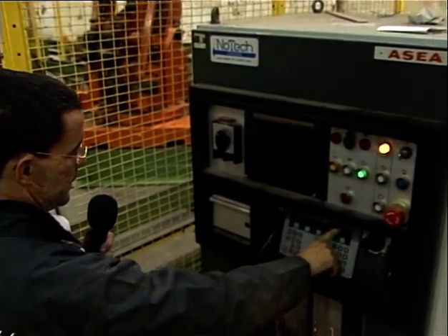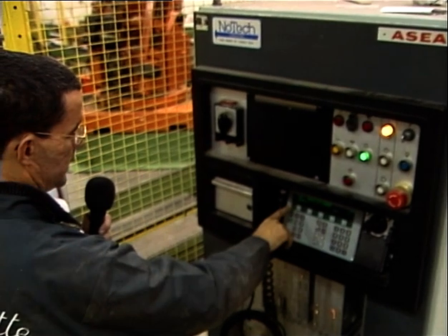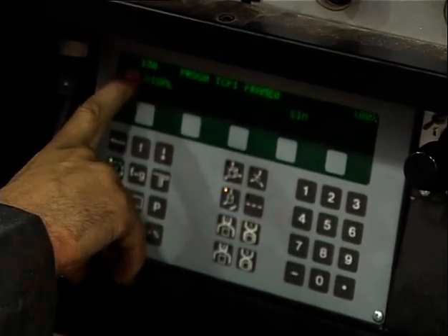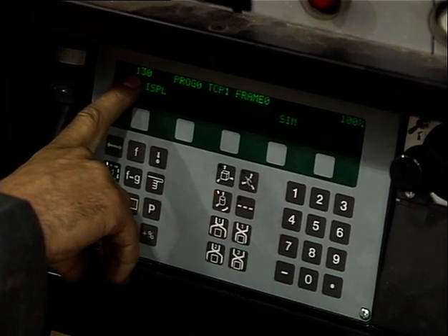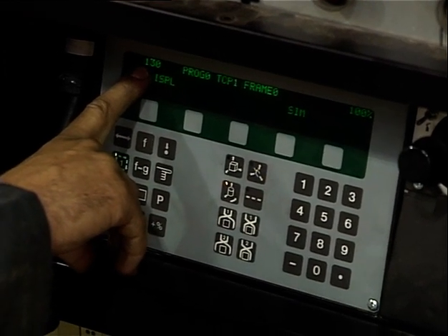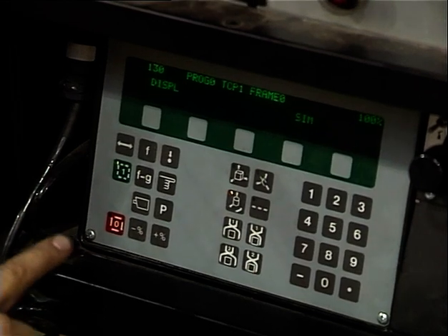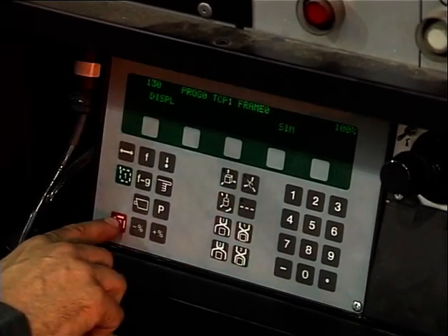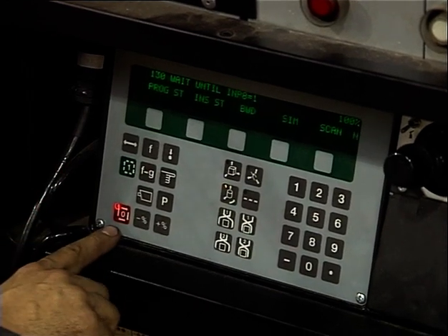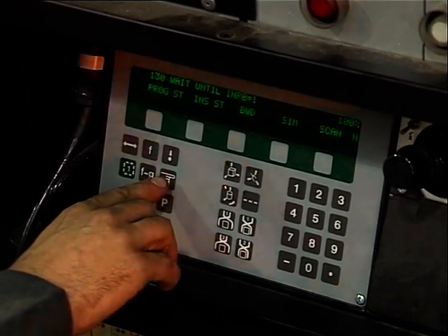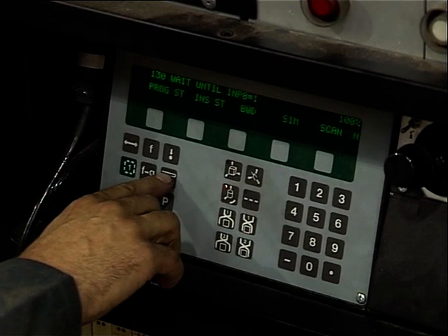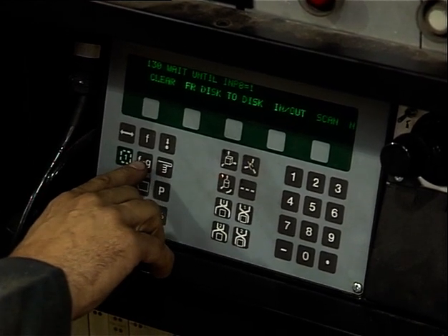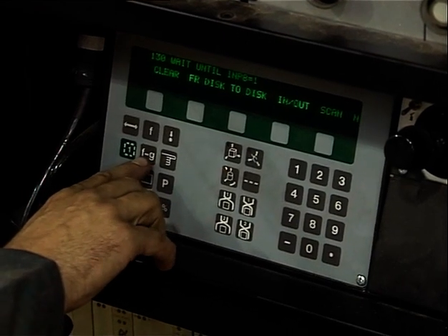You see on the screen of the teach panel the instruction number, but in this stage you are not able to say in which program you are, and I will explain now how you can see that. Therefore, you push on the 0 button. Thereafter, you push on the manual mode button. And thereafter on the FG button.